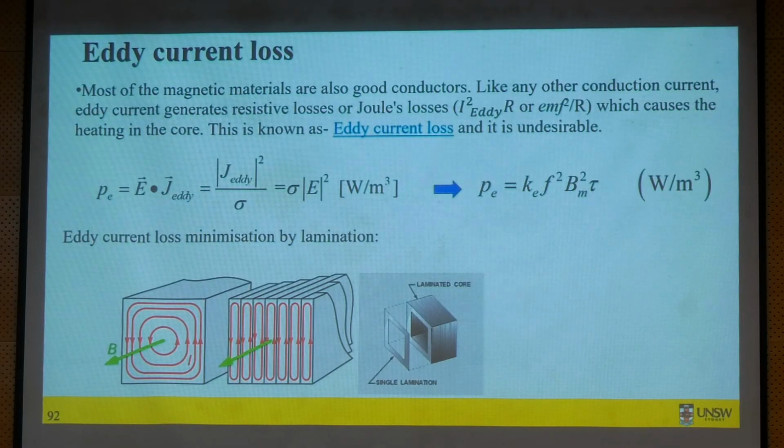Okay, and how do we reduce eddy current loss in the magnet? Same concept as we use for steel material. We can segment the magnets. Okay, instead of using one single piece of magnet, you can use a stack of magnets. Okay, something like this, which can reduce your eddy current loss, if you see in your design there is an issue of eddy current.